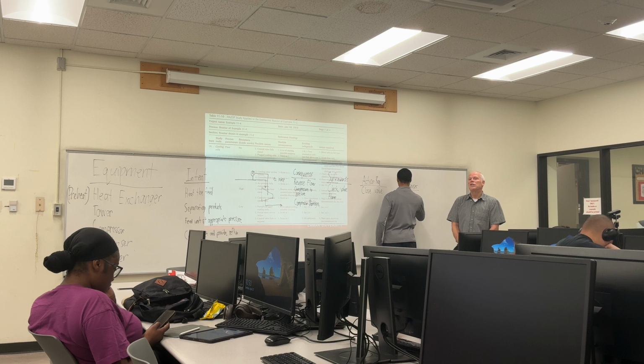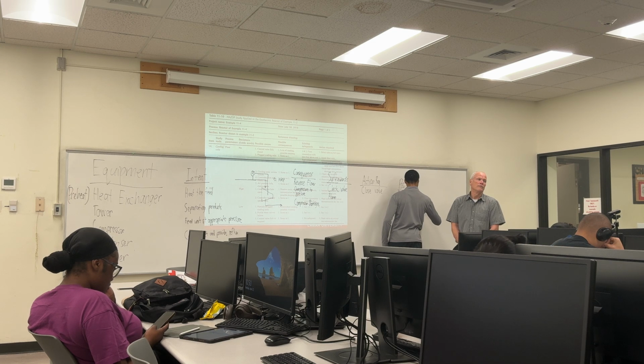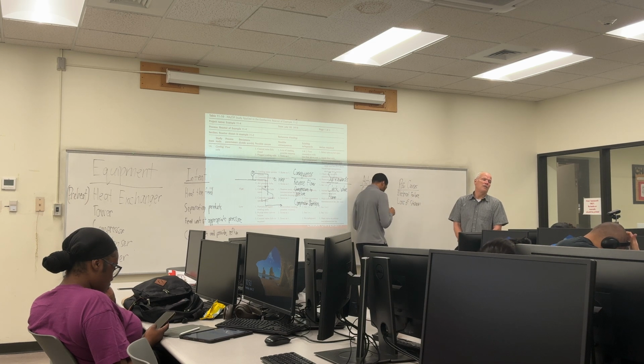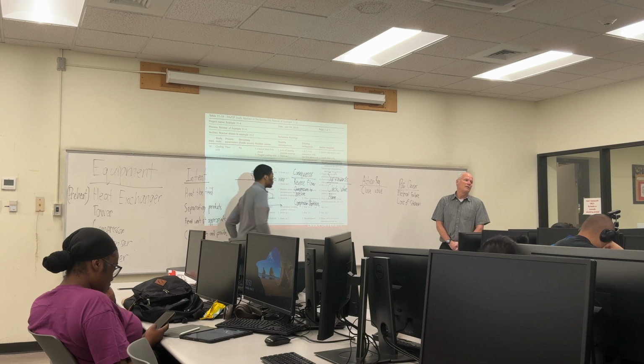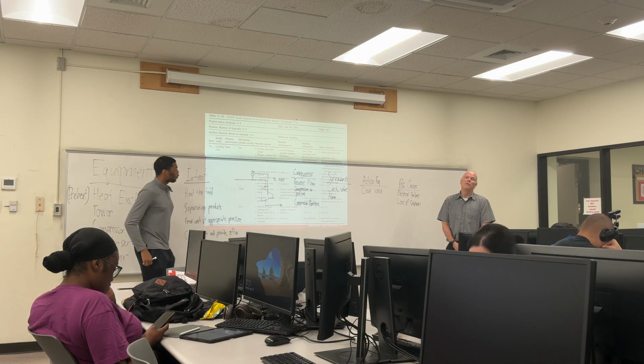So what can happen to stop your compressor from working? The steam turbine driver stops driving it. Well, why does the driver stop driving it? No steam. Yeah, maybe it's a steam turbine and you lost steam. That's a scenario. Right? What else? Motor, turbine, I guess. Well, let's stick with whatever we chose. We chose a steam turbine. What else could cause it?